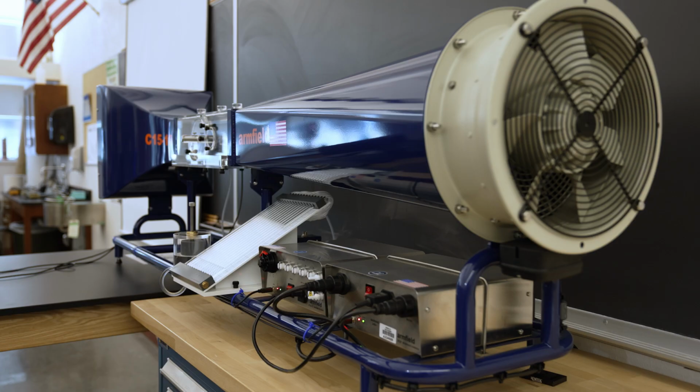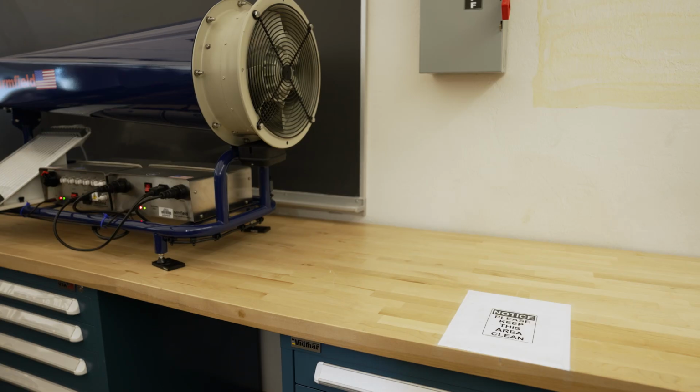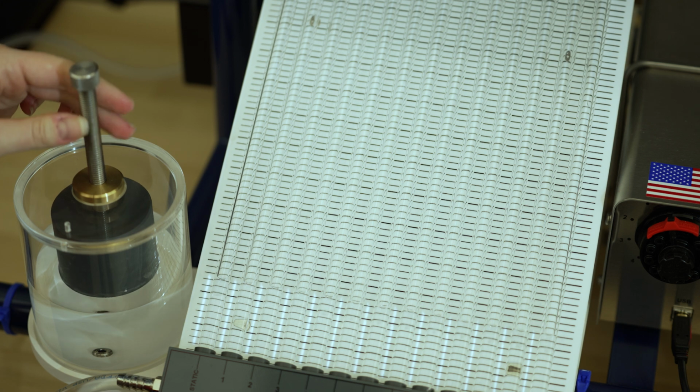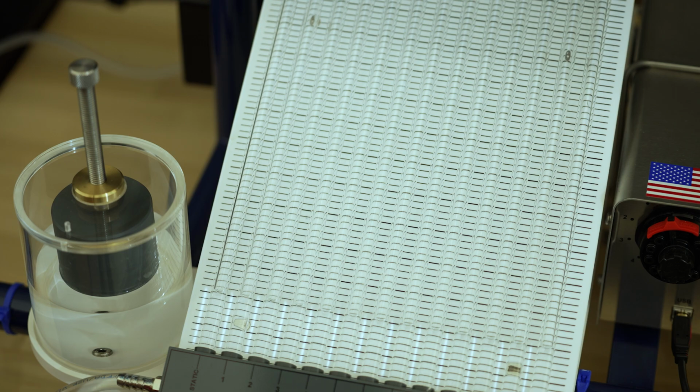Before operating the machine, make sure to wear safety goggles and adhere to laboratory safety rules. Verify that no objects or obstructions are present at the inlet and outlet of the tunnel. Never insert objects through the inlet and outlet, especially if the fan is spinning. Set the water level at 20 millimeters in the incline manometer. Note that additional water levels for other laboratory activities and filling of the water reservoir may be required.